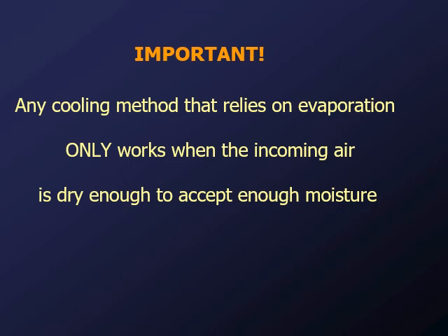So most often we see evaporative cooling working in very dry, hot climates like near deserts. So Texas, Arizona, those are very effective areas for evaporative cooling. Florida, I did mention, but truthfully, Florida's also fairly humid for good chunks of their summer. So swamp coolers down there are still used because they're inexpensive, but they are limited when it's humid out. So just keep that in mind.